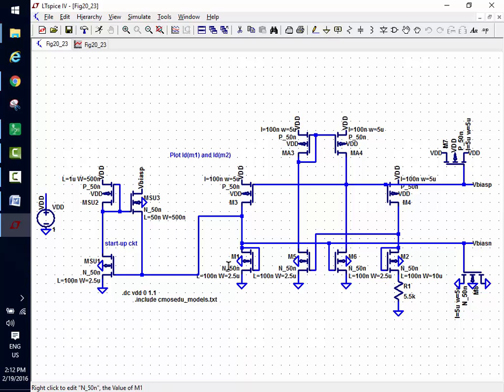So a couple of things. One, if I were to derive the equations governing the operation like I did at the beginning of the lecture today, for this circuit, what would I do different? It's a lot more complicated looking circuit. It's exactly the same derivation. There's my VGS1. That should be equal to the voltage across VGS2 plus ID times 5.5K. Notice in order to get 10 microamps, I had to reduce this a little bit because they don't follow the square law. Instead of 6.5, I use 5.5.